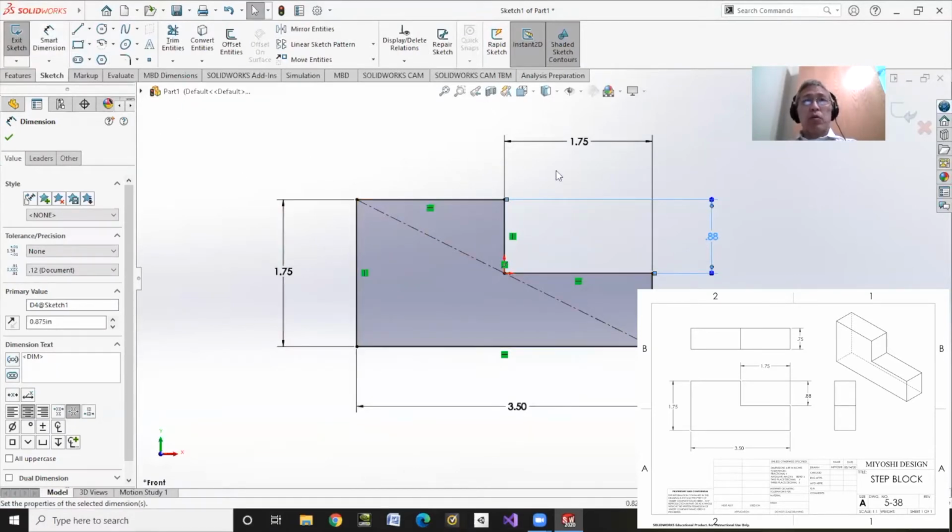Now, I will go through, or hopefully I have made one already, what the different types of lines are. But if you recall, here's an object line, these are extension lines, this is the dimension line. Notice that I can cross extension lines, but I don't ever want to cross dimension lines. So if I had something like this, I don't ever want to do that because that violates the rule of never, ever crossing a dimension line. So try to put these guys in nice, neat places so you have good, beautiful dimensions.